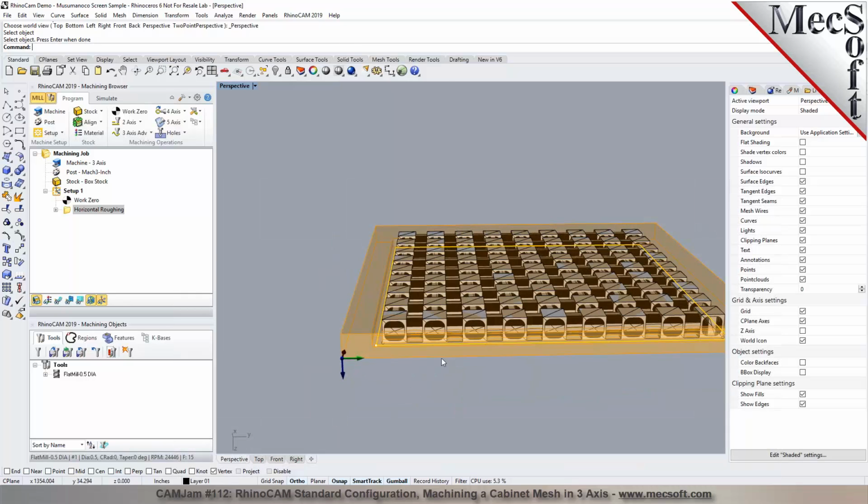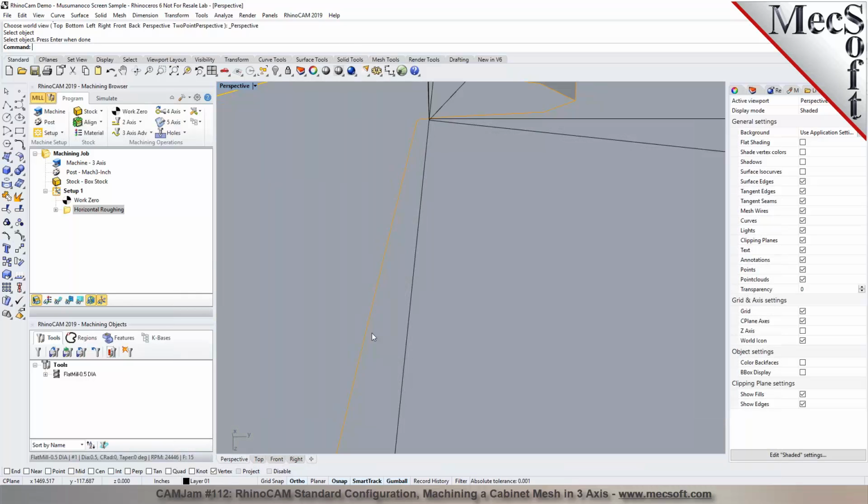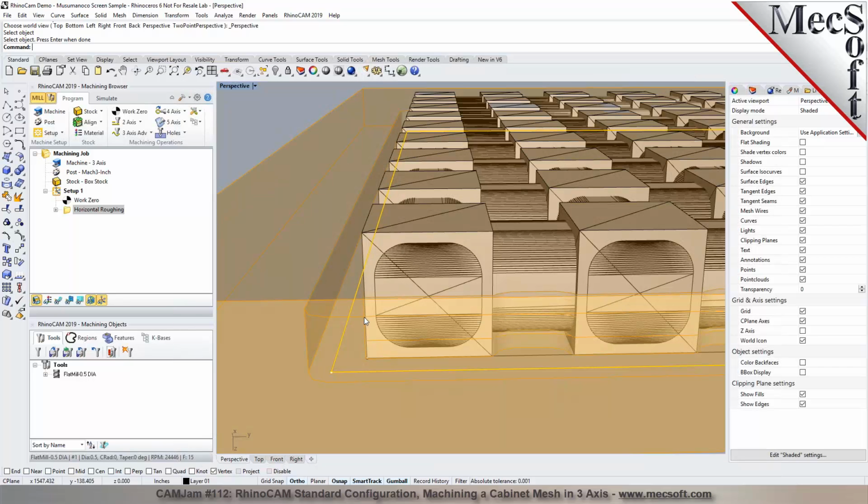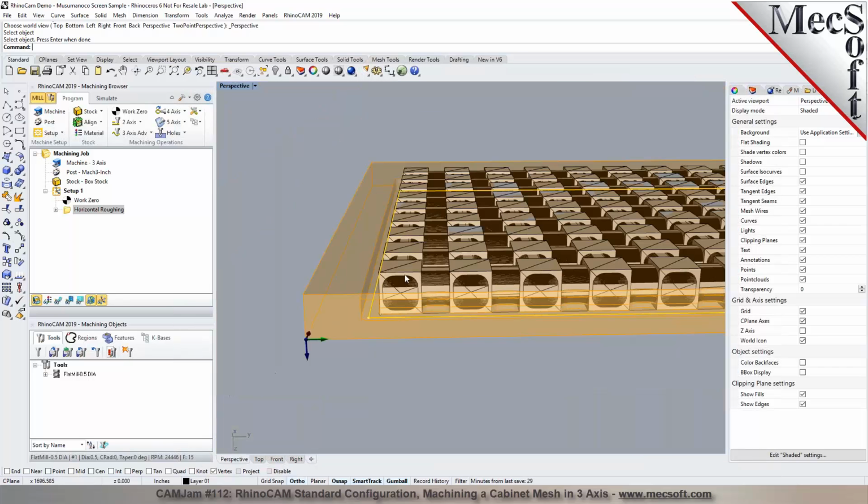You'll see that it's cut down 3/4 of an inch, okay? Now, when you do this other side, it's going to cut down to 3/4 of an inch, and then your part's going to not have any containment. Your stock is actually going to be sitting there, and it's not going to be hard mounted to your holes, all right?